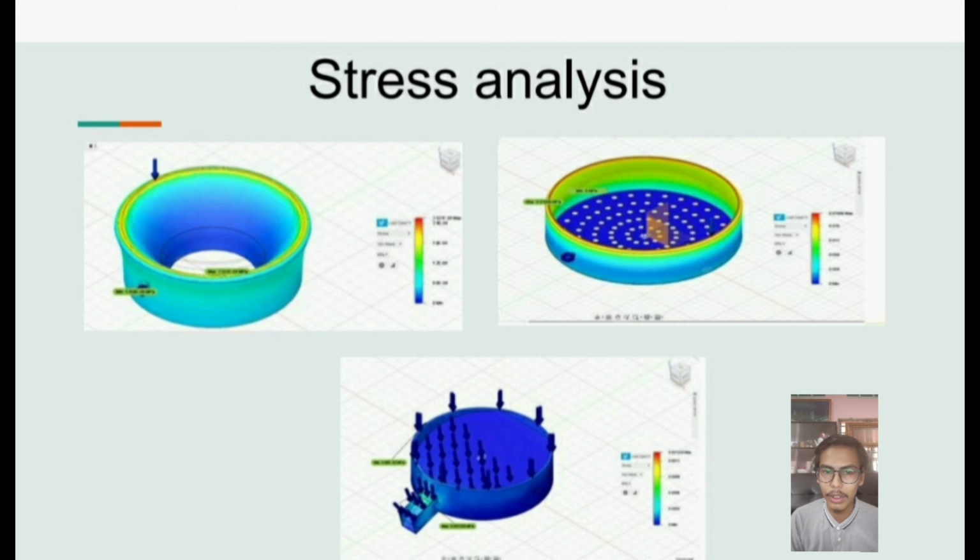Appropriate design factors are based on several considerations, such as the accuracy of prediction on the imposed load, strength, weight estimates, and the environmental effects to which the product will be exposed in service, the consequence of engineering failure, and the cost of over-engineering the component to achieve the factor of safety. For example, components whose failure could result in substantial financial loss, serious injury, or death may use a safety factor of 4 or higher. Non-critical components generally might have a design factor of 2.